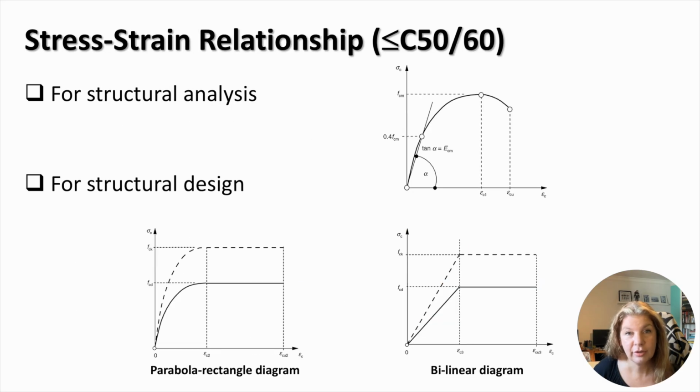The stress strain curve shown in the top diagram is typical for a compression test. As you can see, the curve is nonlinear and difficult to describe using an analytical expression. Such complex curves are used in numerical and finite element analysis of concrete structures.